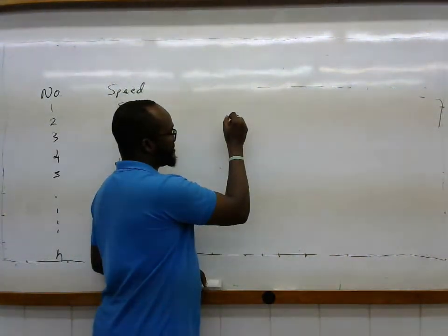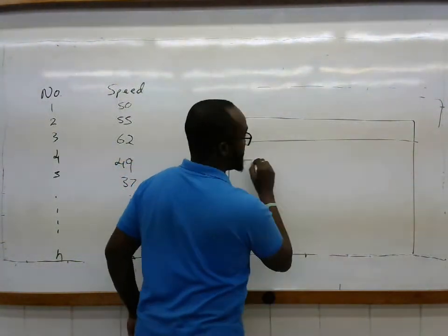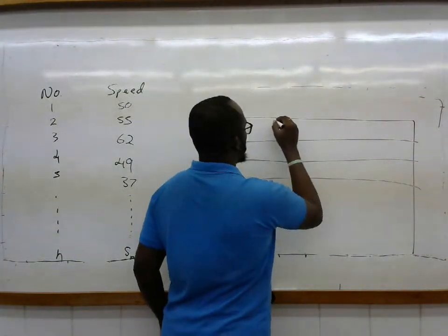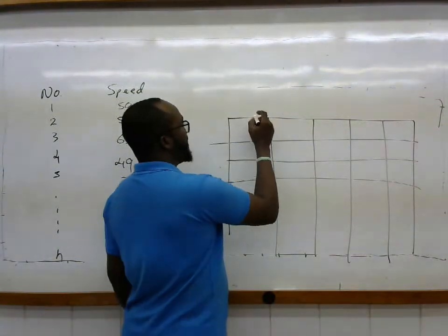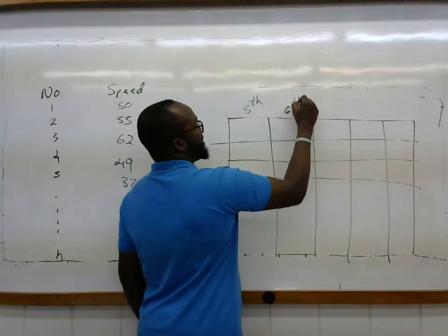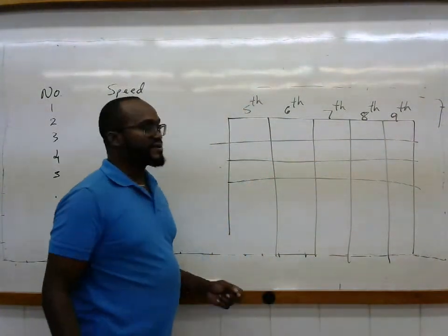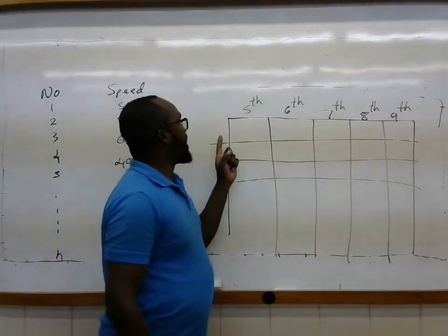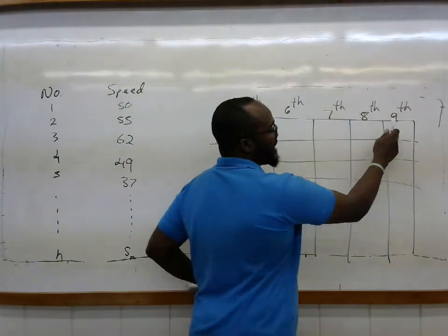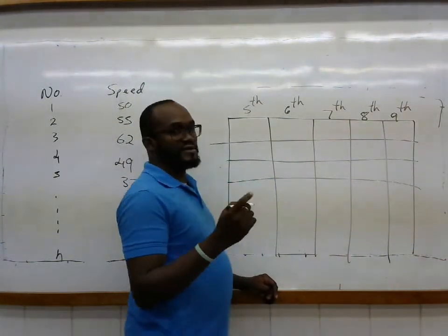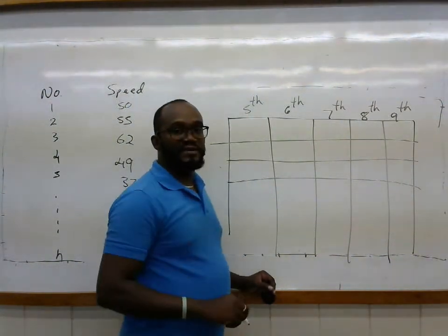So you would have had your tables in the field, and I would have been on site with you, and you would have been taking recordings using a stopwatch after the fourth vehicle had passed, randomly choosing either the fifth, sixth, seventh, eighth, or ninth vehicle to actually record the time it took to cross the stop bar after the fourth vehicle had actually passed the stop bar.